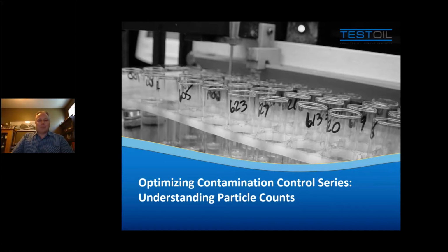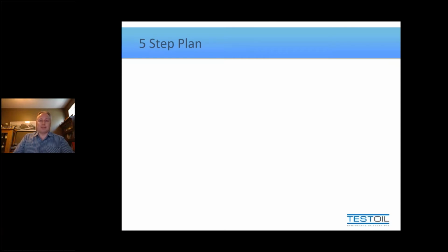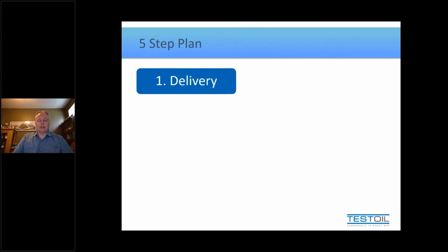Great, thank you, Heather. So yes, this presentation is part of a series. There's 3 parts to this series, and essentially the 3 sections are going to go over 5 steps. So this is kind of a cradle to grave handling of lubricants overview is what we'll be discussing. But step 1 begins with taking delivery of your new oil. And one of the key things about delivery of new oil is that we have to set a target cleanliness for how clean we want it to be. And one of the parts of that is we have to understand that new oil simply is not that clean.